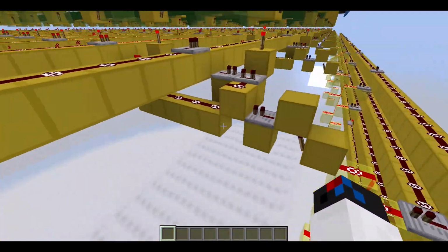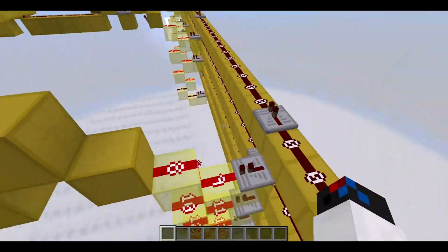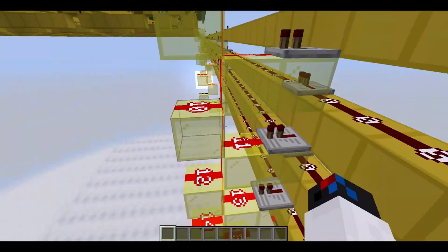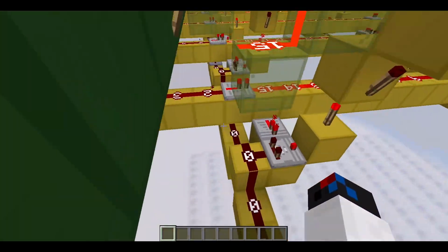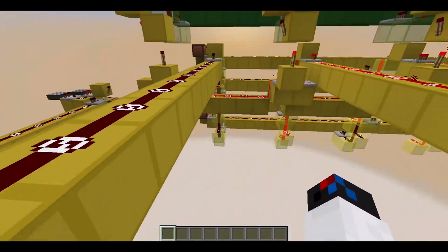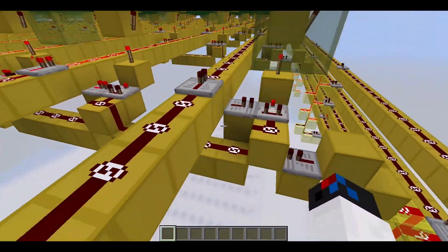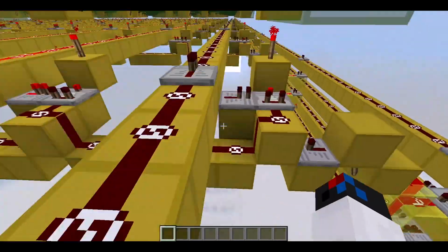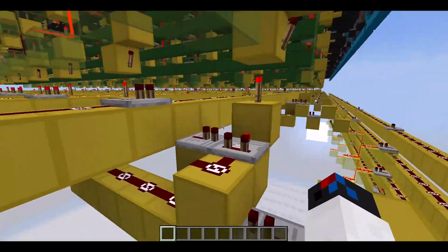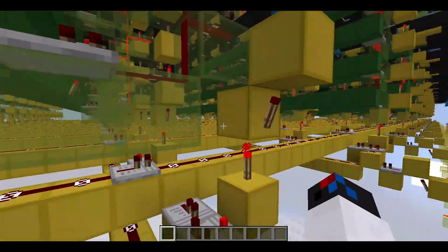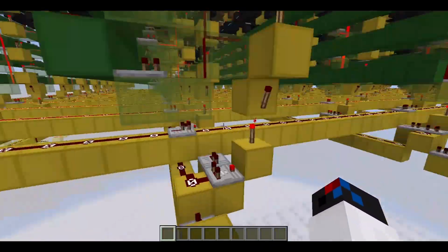And when both decoders select one, so for example, this decoder selects this right here, so all of the lines here turn on, and then this decoder selects this, so now all of these lines turn on, and the cross section between those two outputs will be connected here. So now only this cell is being chosen.